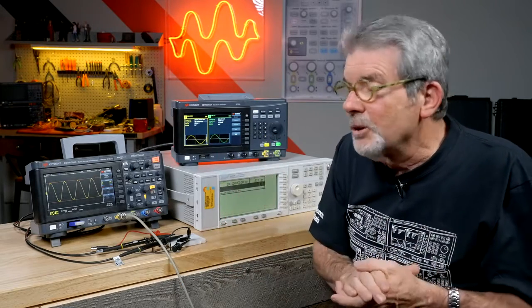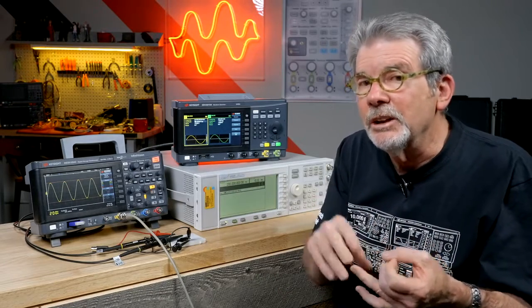Now, you may also be familiar with Nyquist, who says all you need for sampling is 2 times the highest frequency. But this is not a perfect world. The highest frequency is not the same as bandwidth. There's a white paper I wrote, I'll reference at the end of this lesson, that you can download that does a deep dive into Nyquist and why it doesn't quite apply to an oscilloscope.